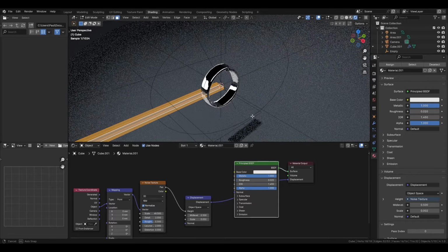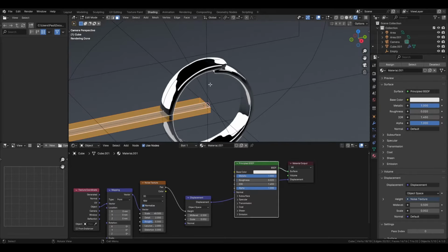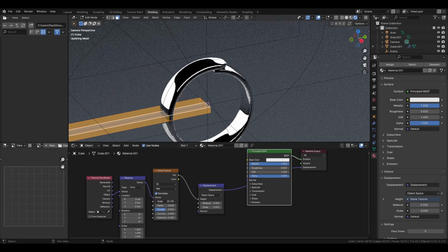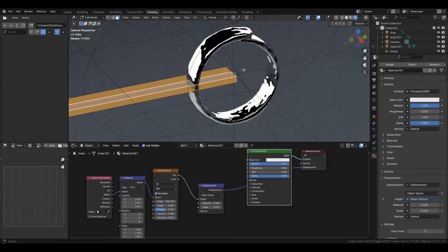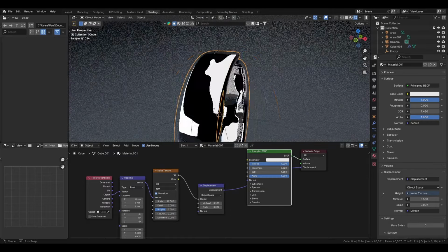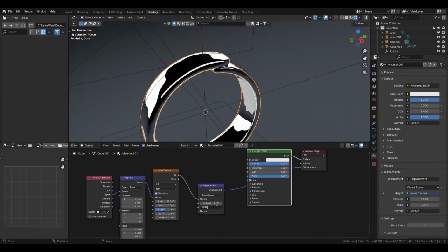Yeah, actually that's not too bad. If you look in your camera, you see that the reflections are not exactly straight, and that's what we want. You can always change this if you want to add impurities into your object. I don't want something too rough, I still want something quite shiny and smooth, so I'll keep this low like this. Maybe that's even too big. 0.01.